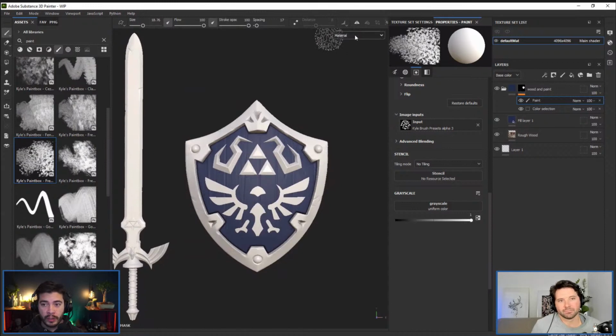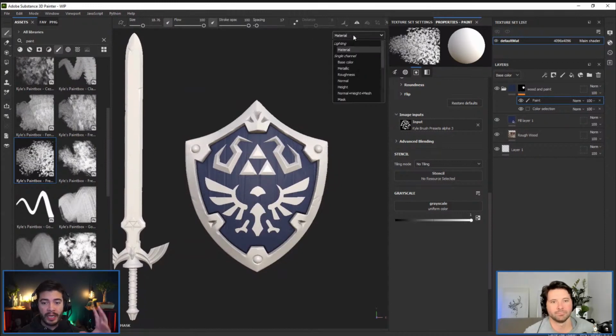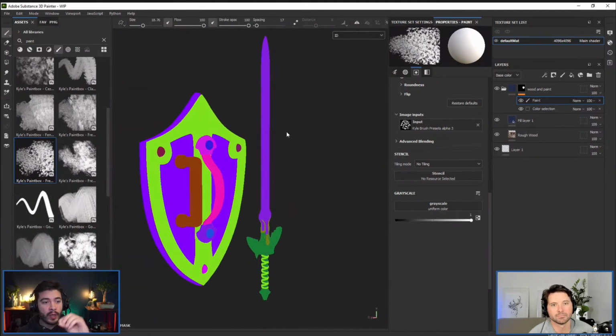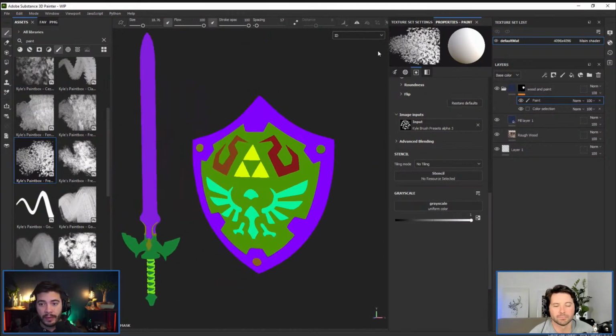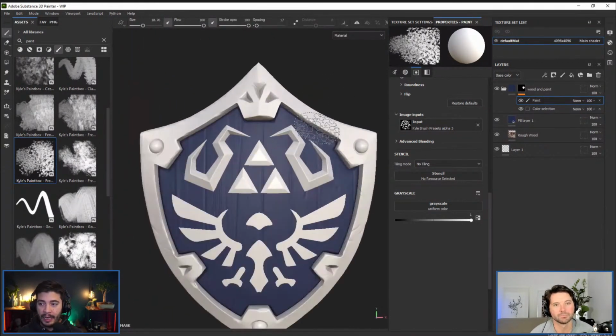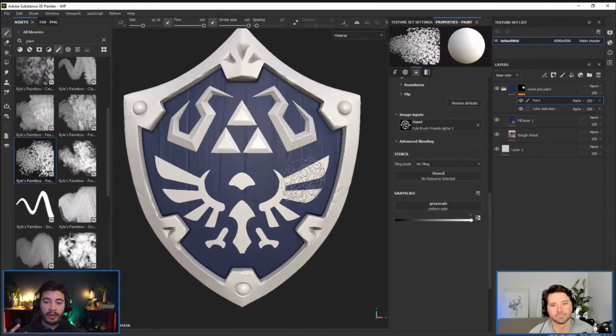But if you go here to the top where it says material, I'm seeing everything combined, but you can see it individually. So you can scroll to the mesh maps, those are the images that I imported yesterday, and go to ID, and then you'll see this is the ID. So you can select very quickly different colors and different pieces to assign materials and create masks like this. Yeah. And then just to go back to the material, you can press the letter M, very convenient for material. And that's it.